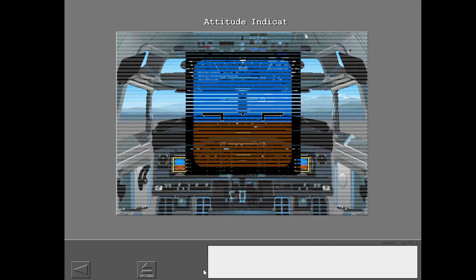The altitude alert is steady for altitude acquisition, and flashes during altitude deviation. Altitude alert is discussed in detail in a different lesson. A failure flag is shown when the altimeter fails. All altimeter displays are removed except the altitude alert and the barometric setting readout.